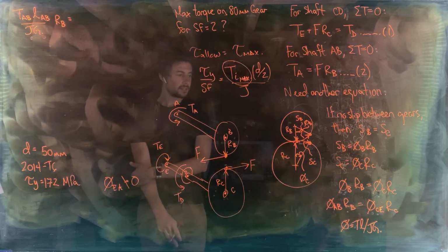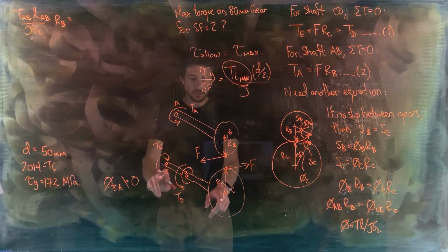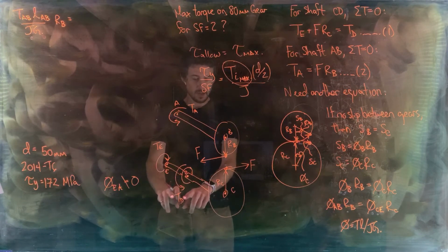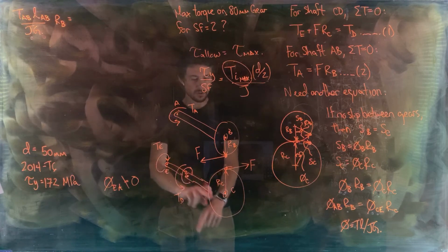Now for shaft CE, actually, looking down here, we need to break that up into two different segments because we've got an applied torque that occurs along its length.